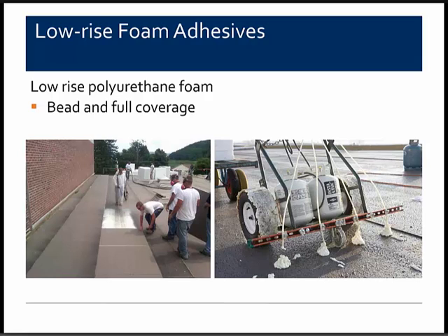On the right-hand side, we have a little trolley device which supports and transports the canisters. The different foam spacings can be adjusted by that little red unistrut device we see, and the bead patterns, or the spacing of the beads, can be adjusted to resist different wind loads that we might find in corners and perimeters, as opposed to the field of the membrane.